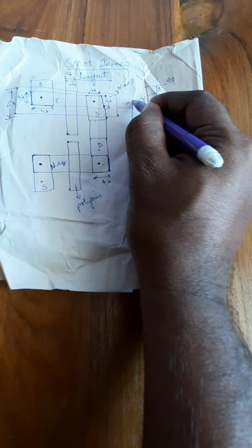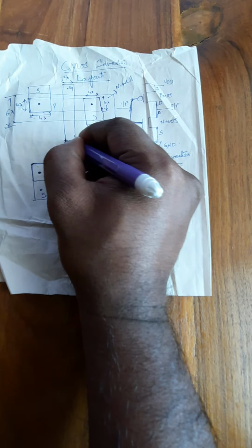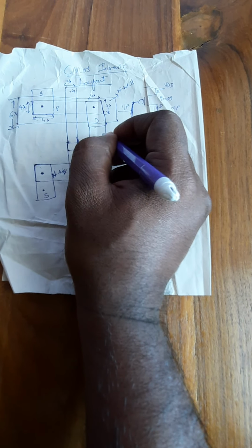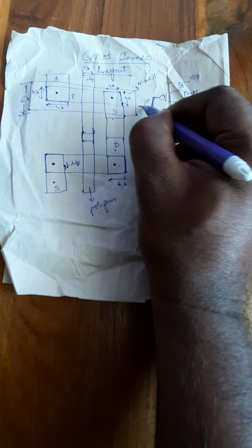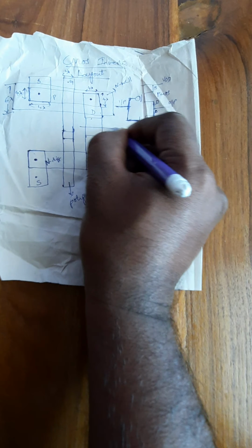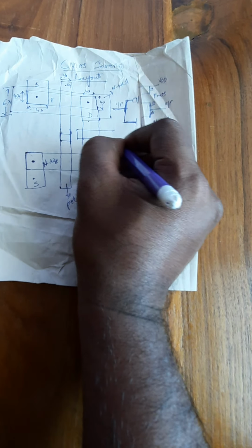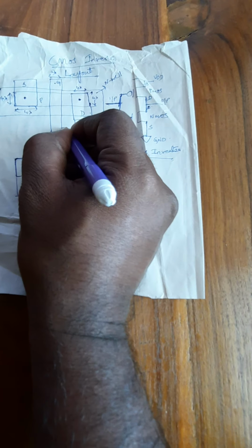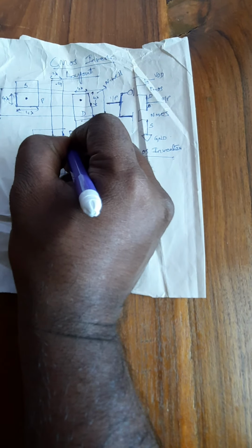Same. Now you can see the input is connected at the shorted gate terminal, so you can short this one. One thing you are supposed to keep in your mind, whenever you short the same kind of material, the contact is not required. So once we have completed this part of the layout, now we are supposed to make the input and output connection. So see now, output is given at the shorted drain terminal, so I'll use another kind of metal layer or the similar kind of metal layer, and this will act as my output terminal, and input is connected to the polysilicon, so I'm using a kind of metal layer.